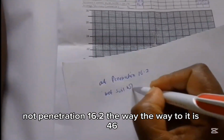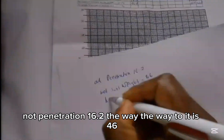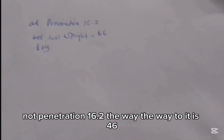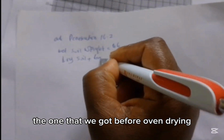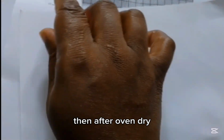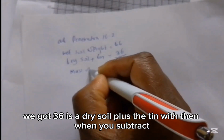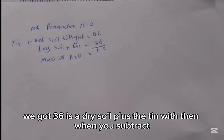Now at penetration 16.2, the wet weight is 46, the one that we got before oven drying. Then after oven dry, we got 36, the dry soil plus the tin weight.